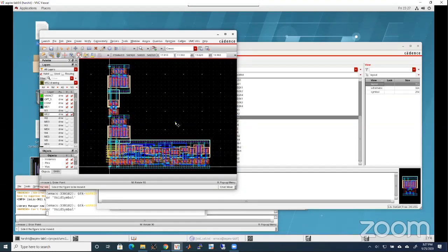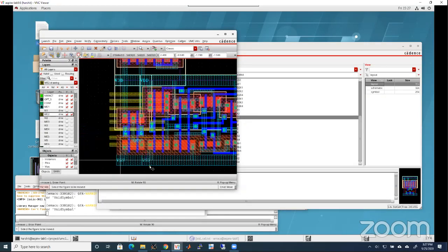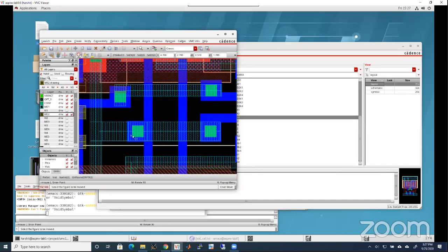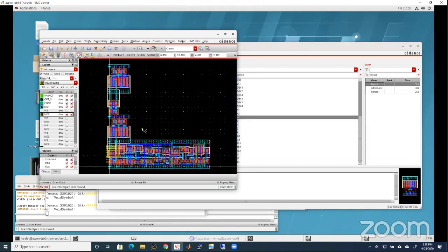Yeah, and the green one are the wire, right? Sorry? The green one, the box from where you have interconnected the metal line and the poly. This is the poly contact. Poly contact. Yeah, okay. So do not use metal 2. So basically the number of tracks defines the spacing between the power and ground rails.